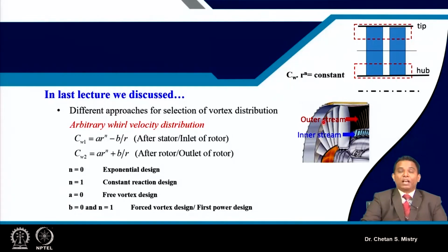Then we were discussing the application of our vortex equation. To be applicable, it needs to satisfy the assumptions we have made. Consider a high bypass ratio fan, where the flow coming out of the fan enters the core engine, and the pressure rise requirement is comparatively low.